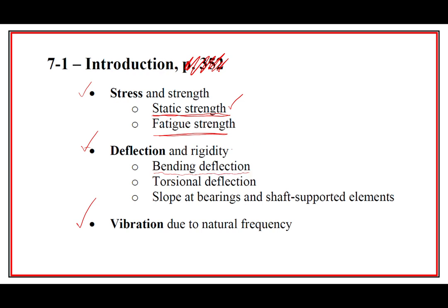A lot of times that has to do with if you have gears involved. You don't want there to be too much deflection, because then the amount of meshing at the gear interface is going to change when the shafts move apart from each other. So you want it to be stiff enough so that it doesn't have a negative impact on how the gears are interfacing with each other.